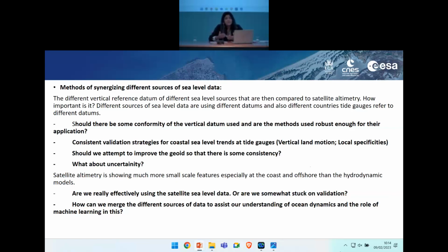And it's also important to know what corrections were applied in the tide gauges that you get. Sometimes you download tide gauge data and you don't know what corrections they've actually implemented in processing it. Have they considered land uplift? How did they detide? What did they actually do? This is why it's important to know the data sets and also the uncertainty, and the method used to calculate it. When you go to validation and to putting products out there, you need to consider these aspects too.